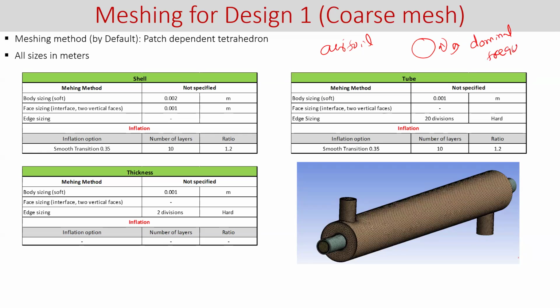So we have the methods to discuss. How do you get the dominant frequency? Actually, I will get the dominant frequency from the Strouhal number. From the Strouhal number we can get the actual frequency, and based on that frequency, we can get the total time it will take to pass one vortex shedding cycle.